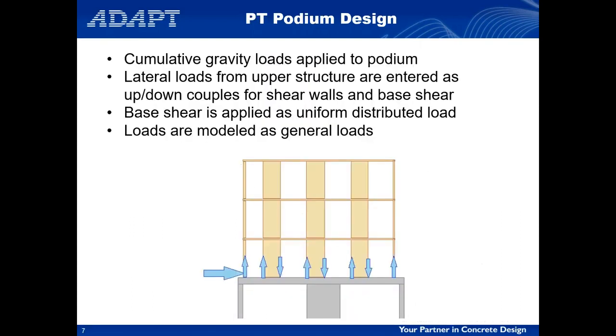So let's start talking about the process. We're going to assume that you've used some external program, whether it's RISA, Tekla Structure, or one of the many proprietary systems that actually deliver the base shear and the individual shear wall coupling loads for the superstructure. We're going to go ahead and assume that we have those loads.